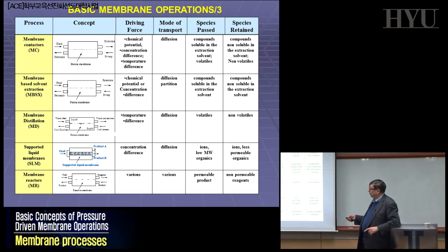For example, in principle here, the selectivity is 100%, because no sodium chloride is going into the vapor phase, so it will not go across. When you're talking about selectivity in reverse osmosis, theoretically, you cannot have 100%. There is always a difference in the concentration of some ions across the system. It can be very high, but will never be 100% by definition. So that's what we will discuss with some attention.